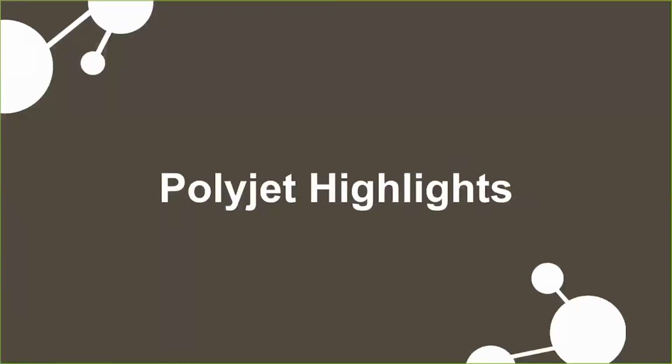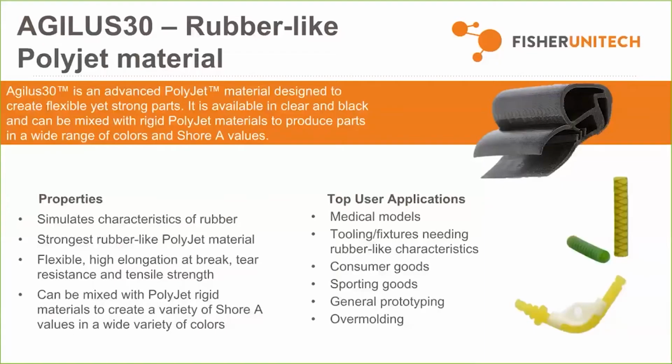And just a quick few highlights about PolyJet technology, and we'll get right into DFAM. One of the newest materials for the PolyJet line is called Agilis 30. It's meant to simulate rubber material. By its name and its basic form, it's a Shore A30 material. But due to the fact that it's PolyJet technology based, rigid materials can be added to it during printing to create a range of materials from Shore A30 to Shore 95.